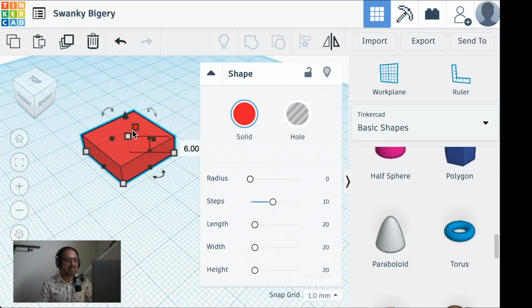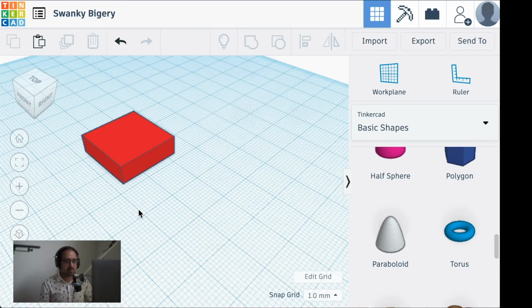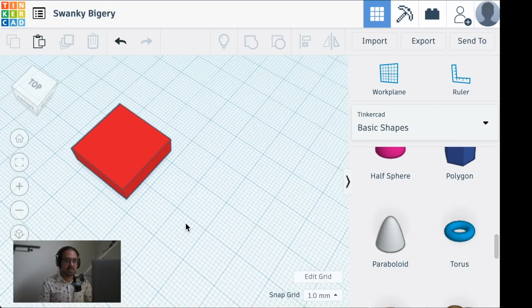but it's about right. You probably know for 3D printing, and especially FDM printing, you don't want to get much thinner than about 1 millimeter, because that starts hitting the limits, and your print will start warping if it gets any thinner than that. So only start doing that once you're a little bit more familiar with what 3D printers can do. But what I've got here is going to be my keyhole shape.